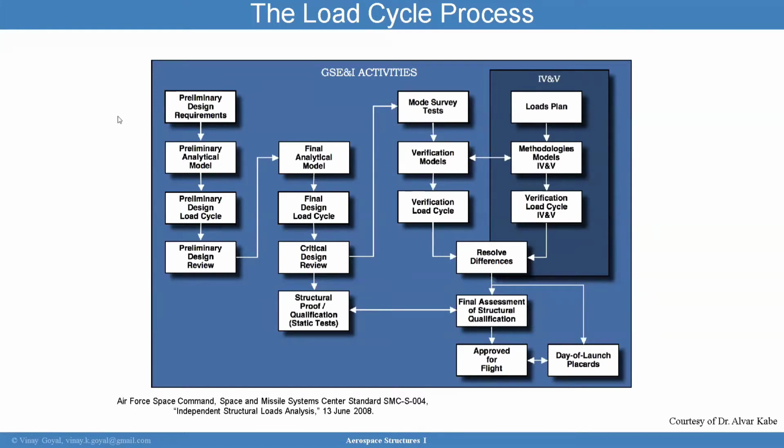So I want to continue discussing the launch availability. To achieve the required launch reliability, many launch vehicles have to be placarded. The placards can be divided into two families. One is a launch placard, and the other one is a flight placard. The launch placard typically will include ground winds, for example, and lightning, cloud cover, temperature, or something else. Atmospheric flight placards, however, include flight loads, trajectory, control performance, and things like that.